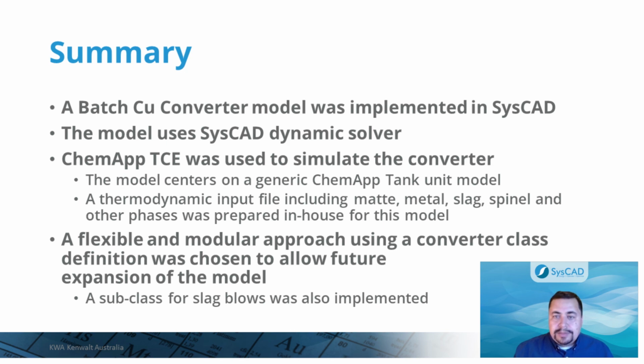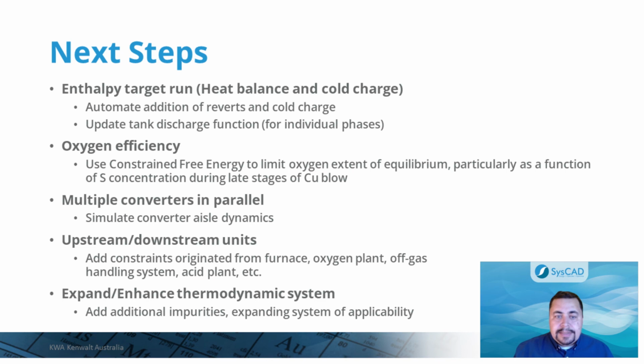temperature management. The next steps for this model include finalizing enthalpy target runs and automating the addition of reverts and cold charge for temperature control, and implementing oxygen efficiency using the constrained free energy method to limit the extent of oxygen equilibrium, particularly as a function of sulfur concentration during the late stages of the copper blow.